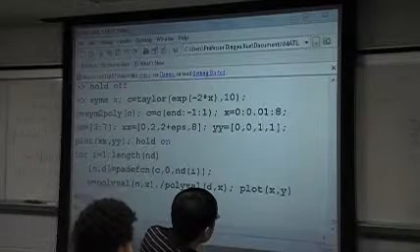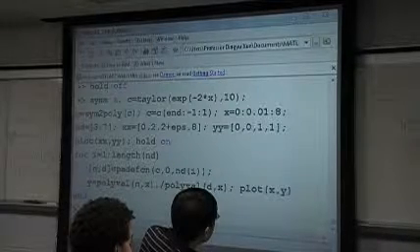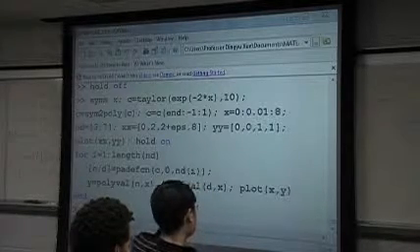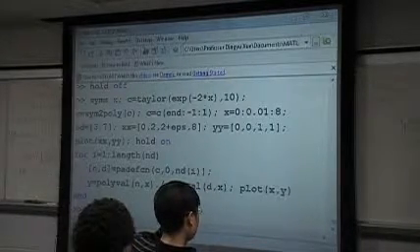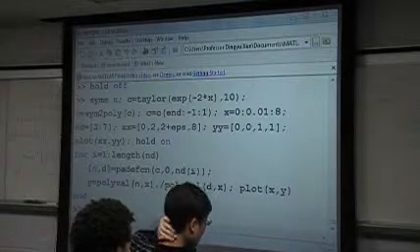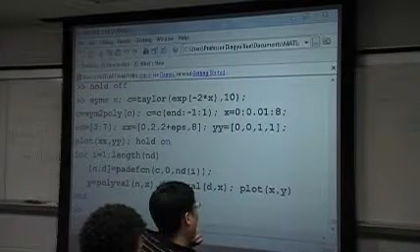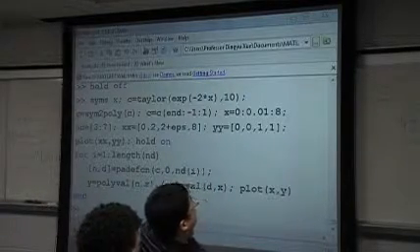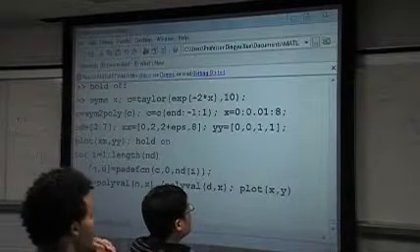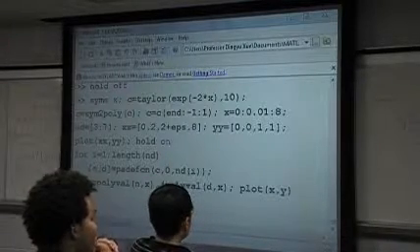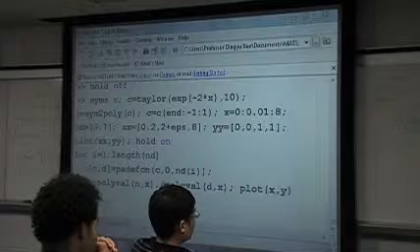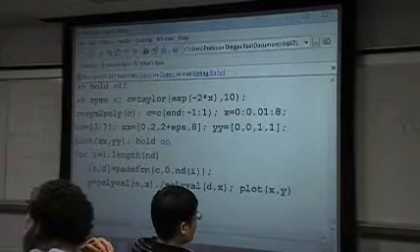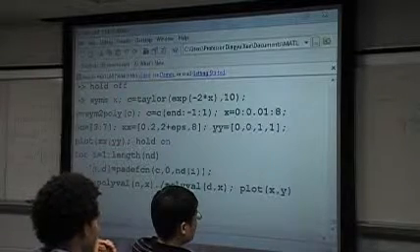So this part can be expressed by a transfer function, but the closed loop system cannot be expressed by a transfer function. So what we normally do is to replace this one. This one should be minus. If we replace this one by a rational function or transfer function, then we can solve this problem easily. Approximation. Yes, you can use Padé approximation. Otherwise, you cannot find a closed loop system if there is a time delay in the open loop.